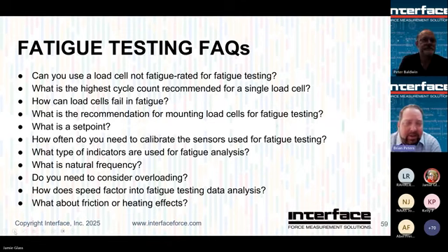But in our experience, by the time you factor in the actual loads, which changes the system level natural frequency, things are typically operating around 60 hertz for most force testing. That's still pretty quick. Obviously, if you're going faster than that, we can get with you on that. But natural frequency is just good to understand the mechanical aspect and understand how it impacts. Again, think of a load cell as a spring, very stiff one, but still a spring.